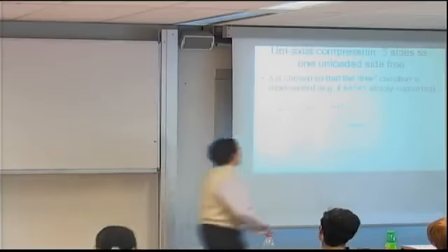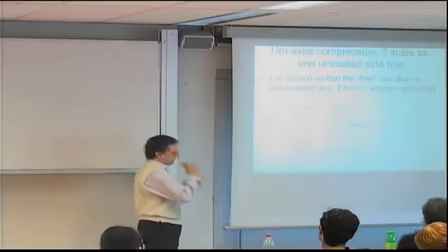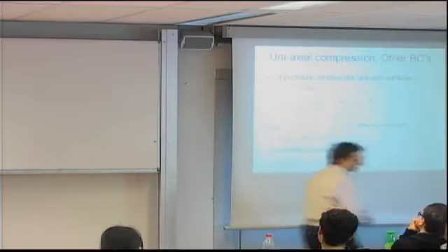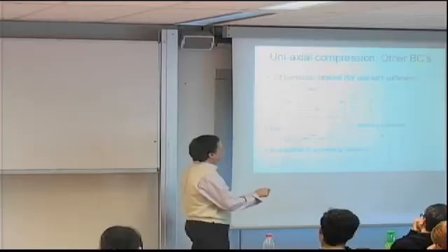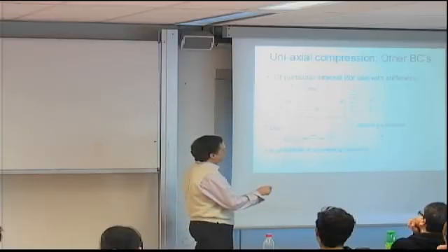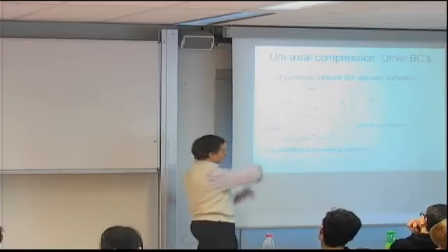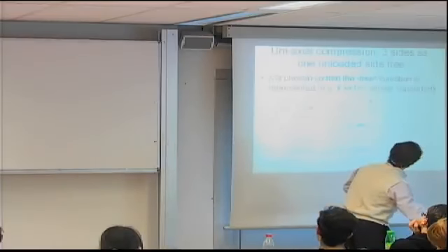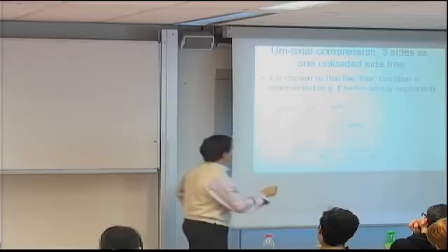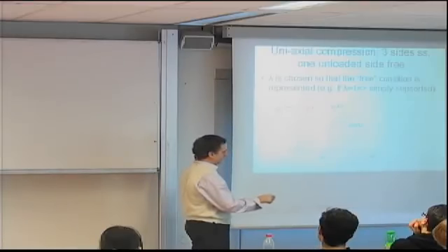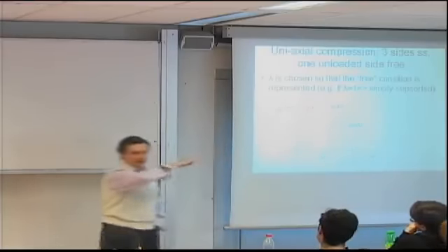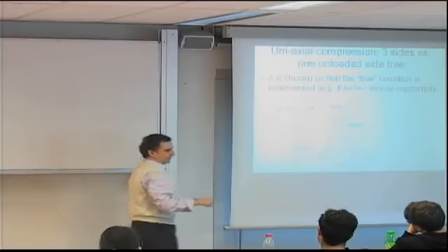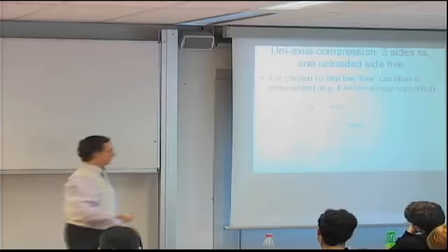And if you think lambda is 1, then my sine lambda, let me back up again. Remember this term, sine lambda n pi y over b. So if lambda is 1, I get sine n pi y over b, which, for the case of n equals 1, is exactly what we had before. It goes down to 0 at the other end, the y over b. So this is the end that's supposed to be free. So this is no good, lambda equals 1, because obviously it reproduces a simply supported condition for w.